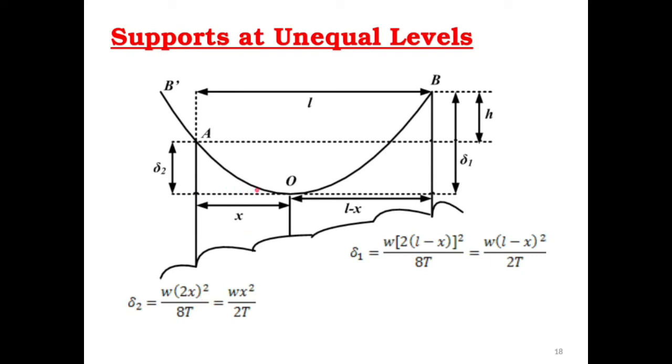For example, now I'm coming to the point of lead time, if you assume that this conductor A or B could be imagined that it is expanded to the D prime, then it's going to look like that parabolic method, and this point O, which is the lowest point of the conductor, will become the middle point of the conductor, meaning this distance x, if we double it, then we can utilize that previous formula from the parabolic method to make it simple and easy.